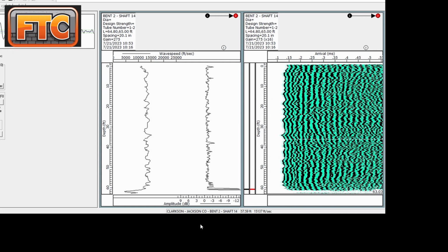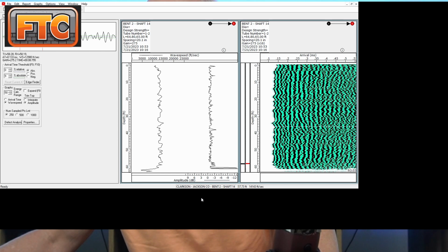So we're going to go through here. This is, in brief, how you would do the analysis. You pick a spot before there's a departure in the velocity at a discrete zone. In this case, our typical sonic velocity is around 13,000 feet per second. So we're going to look at where that velocity decreases by more than 10% and then note it in our report. If you go down here, about here is where we start dropping below 11,000 feet per second.